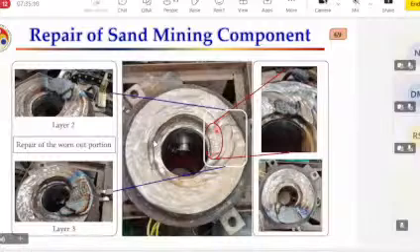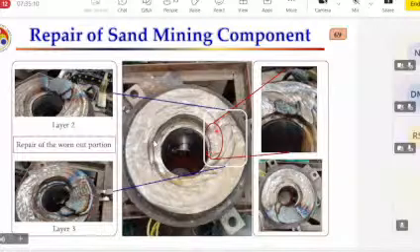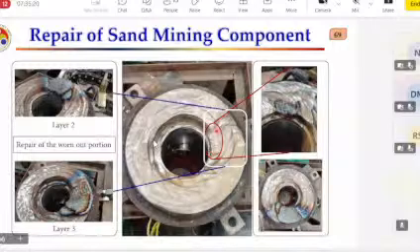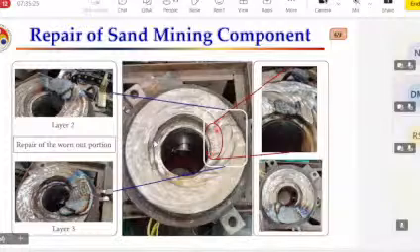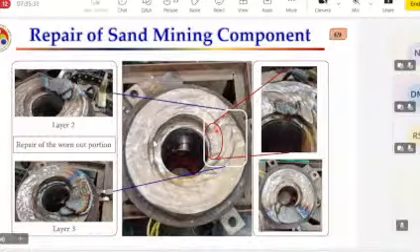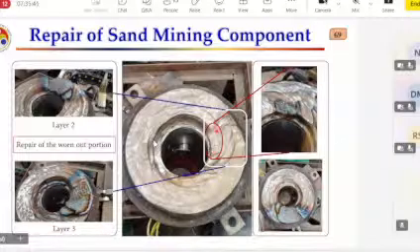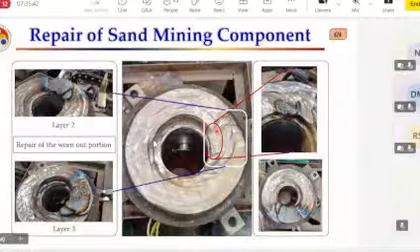And a quite major advantage of this process is that, as you can see, we can reduce the mass by around 8%, and you can reduce the conductivity as well, because these holes have nothing but air in them, so they act as insulating material. Hence, the conductivity has been reduced by 26%. You can reduce it even further if you increase the number of holes in this part, and you can even increase the conductivity of the component as well. Eventually, it will have another advantage like the stresses and all. So these kinds of things we can explain with this framework.